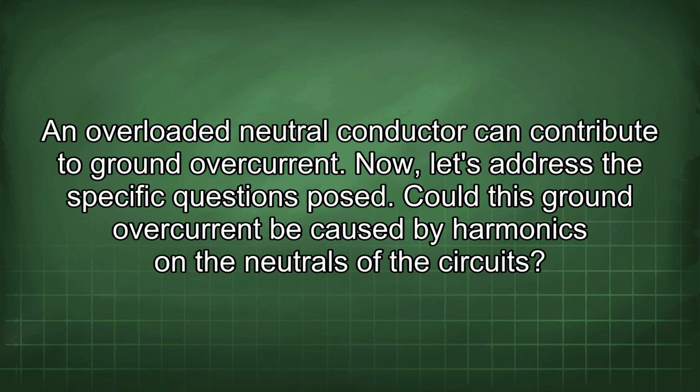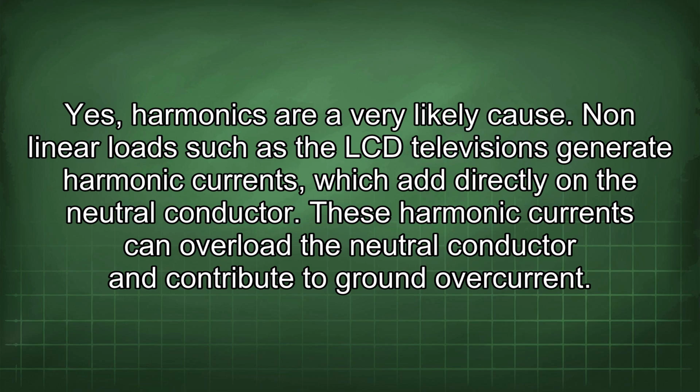Now let's address the specific questions posed. Could this ground overcurrent be caused by harmonics on the neutrals of the circuits? Yes, harmonics are a very likely cause. Nonlinear loads such as the LCD televisions generate harmonic currents which add directly on the neutral conductor. These harmonic currents can overload the neutral conductor and contribute to ground overcurrent.